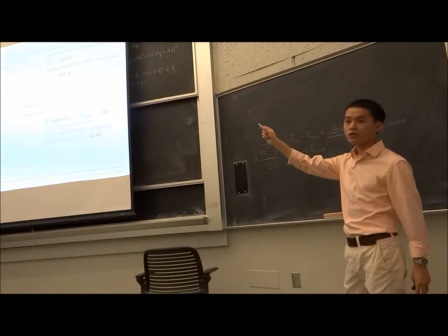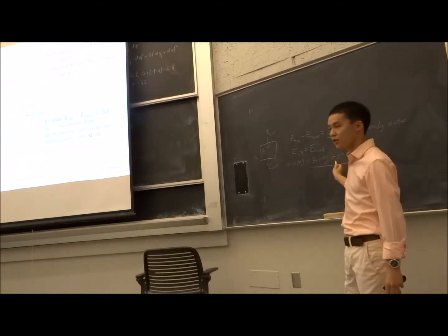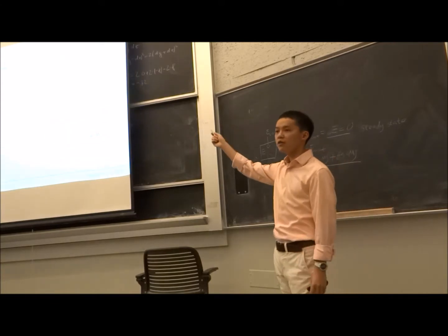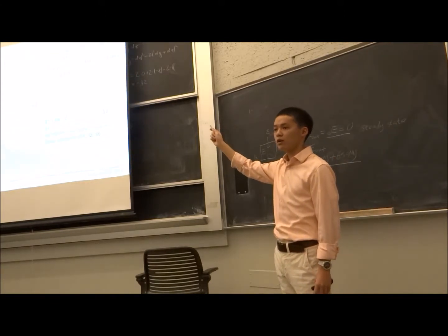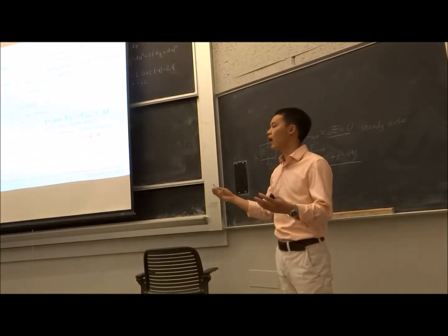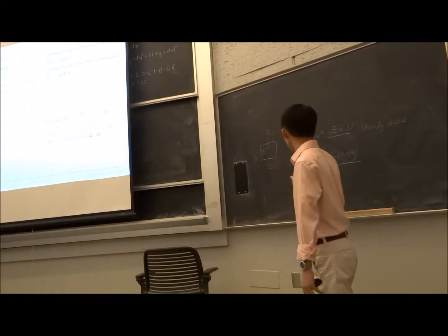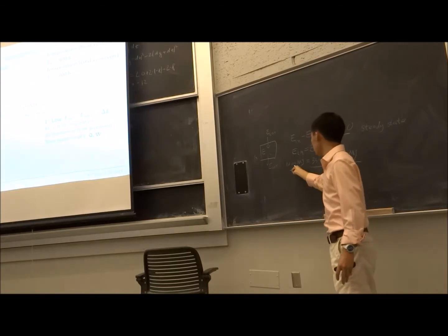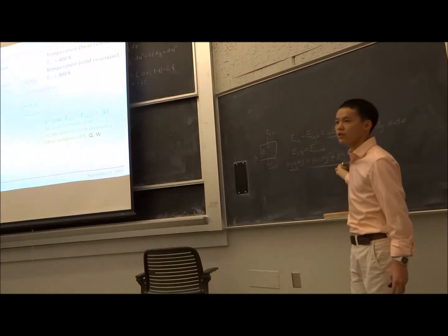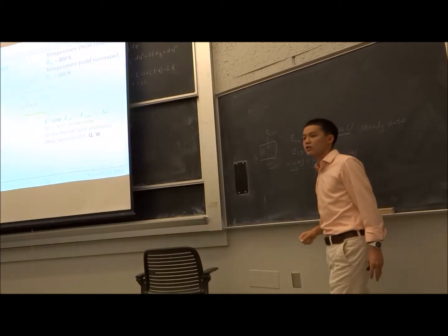Sometimes not all the values are given, so you will need this first law to find them. For example, if you are not given 350 megajoules here, and you're only given 650 megajoules, and I ask you what will be the output for electricity, you will use the first law to find out that our input is 1,000, the waste heat is 650, therefore the electricity is 350.